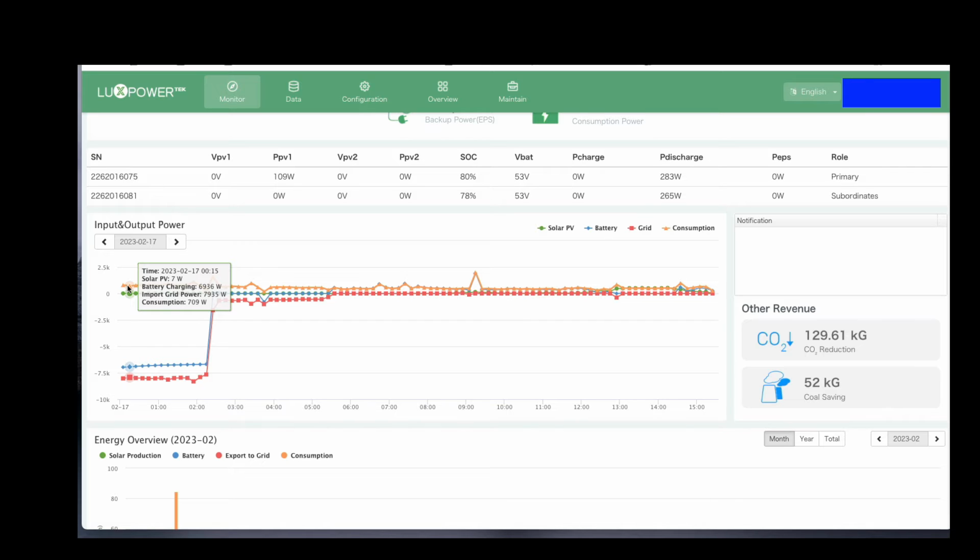The Powerwall pods is what I've got, or if you have the hybrid inverters, they do have charge and discharge rates of 3,500 watts per hour, or 3.5 kilowatts. Some of yours will vary due to temperature. Mine's kept in a storeroom in the kitchen, which is a good temperature. It's not very cold and it's not very hot, and therefore the conditions are pretty good for it to be on maximum. And that's why I've got that.